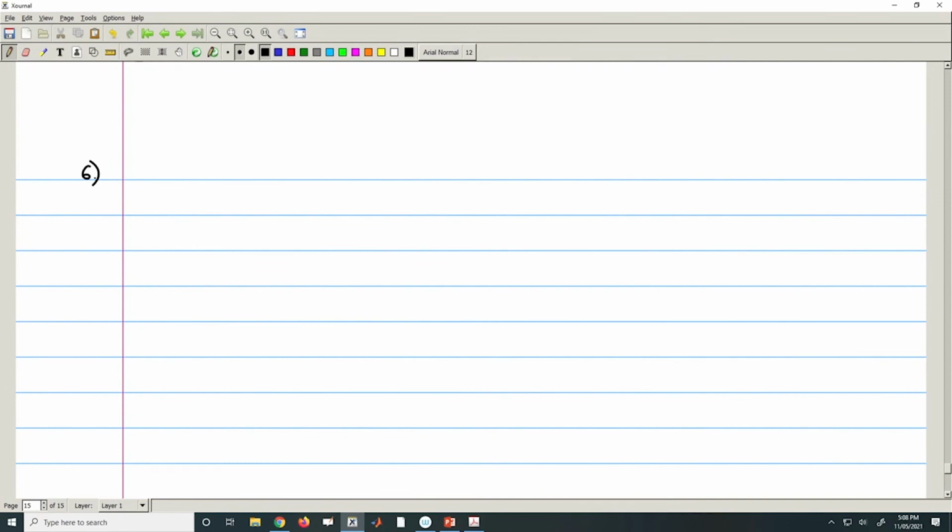So, in the given question there is a 1 centimeter cross 3 centimeter rectangular air filled waveguide, okay, and it is operating in TE12 mode and at a frequency which is 20% higher than the cutoff. Okay. So, we will start with cutoff frequency. So, Fc will be this equation. Okay.